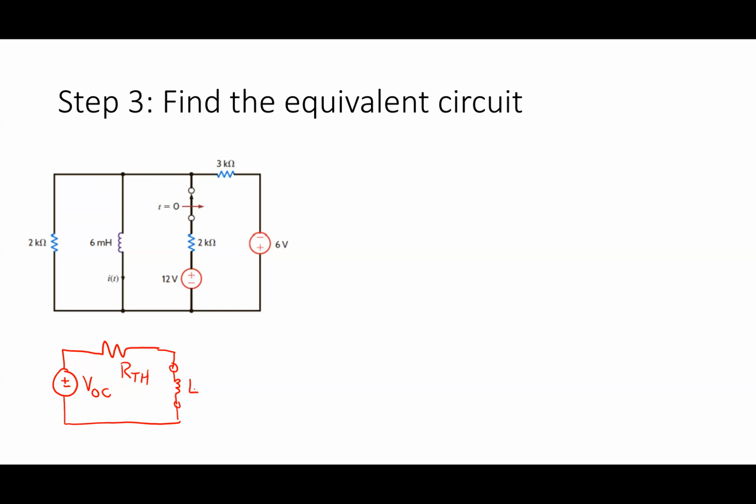So I have to say, what Thevenin equivalent am I making? I got to figure out what I do to this circuit to make that happen. And what time period am I considering when I do this? Between basically time t equal to 0 and infinity. During that time period, do I leave the inductor in? Yeah, I'm leaving the inductor in. But I've got to simplify the circuit.